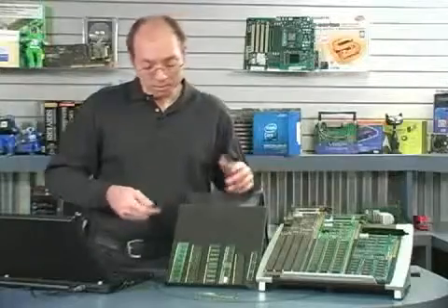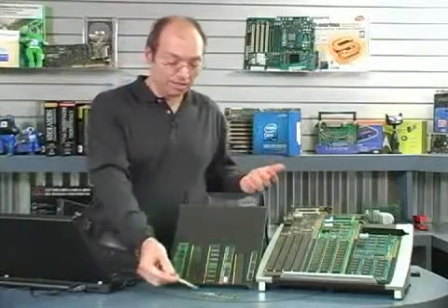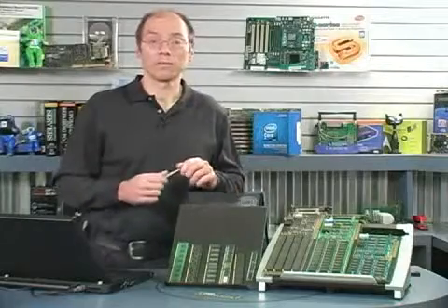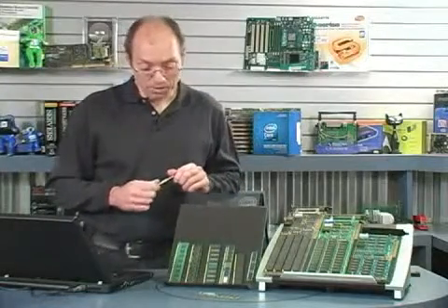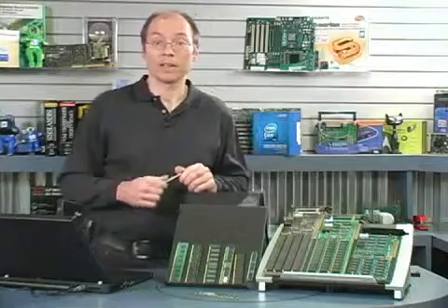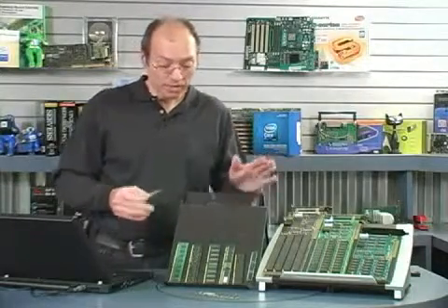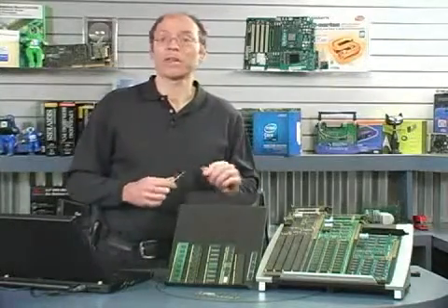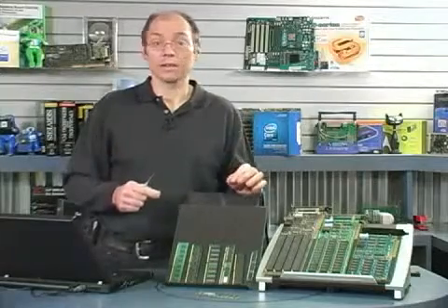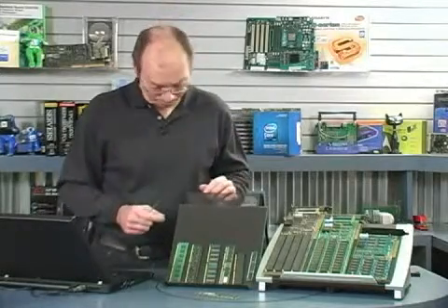in backwards. But even with notches like this, I still come across burnt memory pins fairly frequently when people try to install memory and they don't know exactly what they're doing. So in any case, when you are installing memory, take care to make sure it's fully inserted in the socket and that it's in the right orientation.